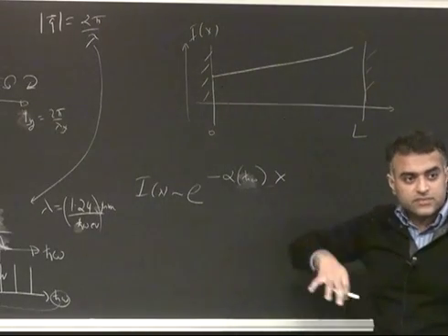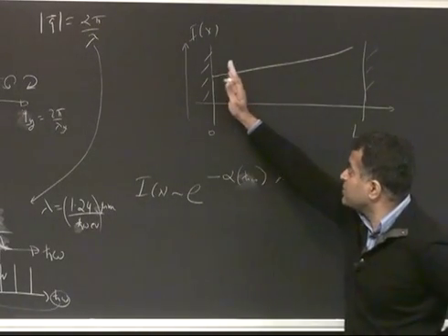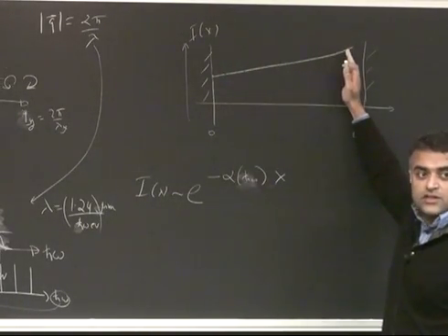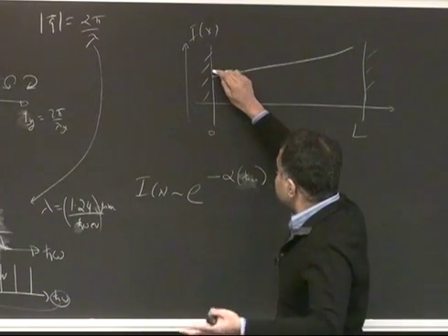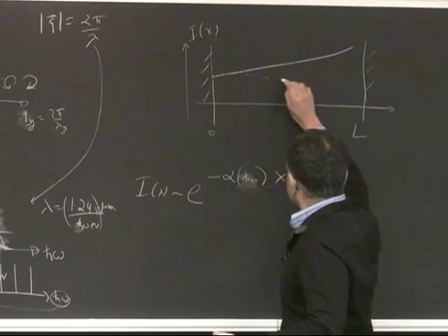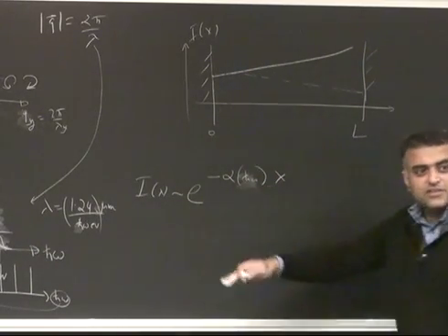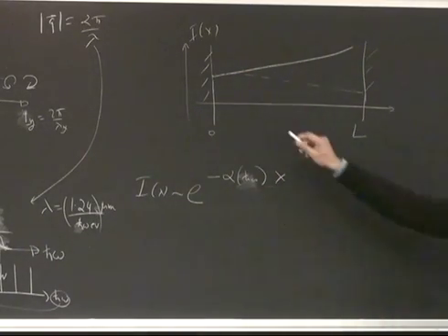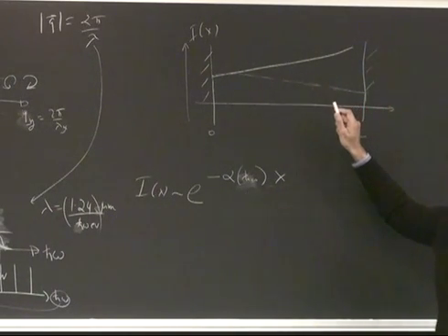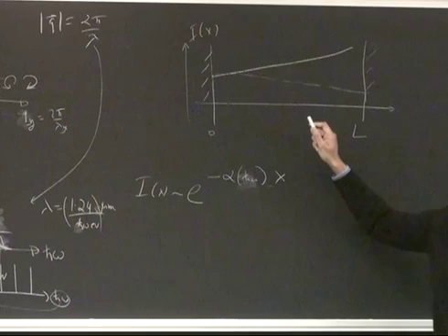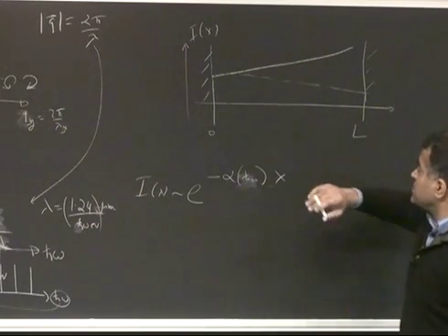Right? It's going to grow, and that's the gain: 10 photons, 15, 20, and so on. But if there is loss, and the loss actually happens in parallel, then it decays, and the question is, you have to fight both. The loss would be non-radiative processes, like Auger, defect-assisted, and all these other things. Same thing as an LED. So you have to balance these out.